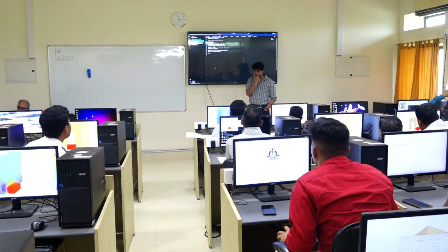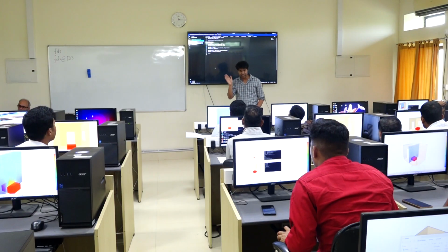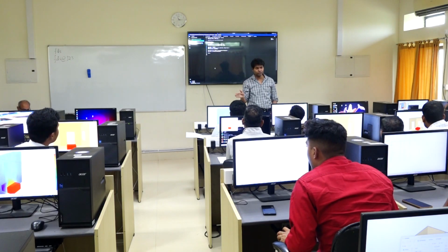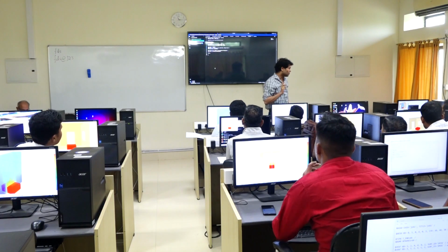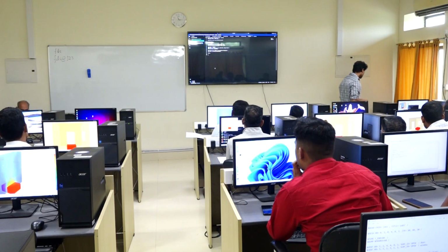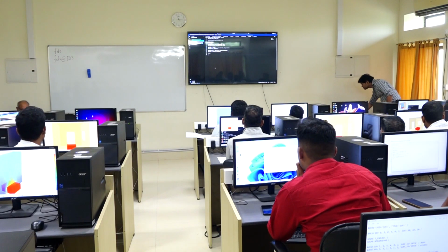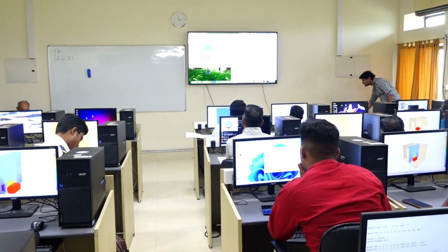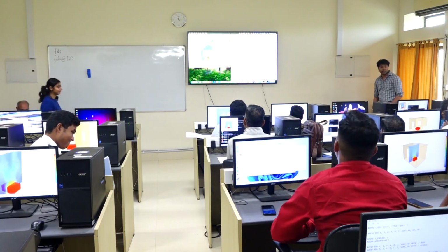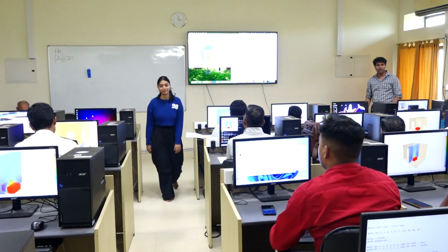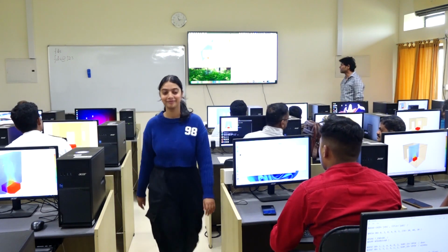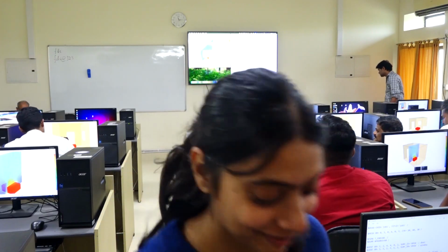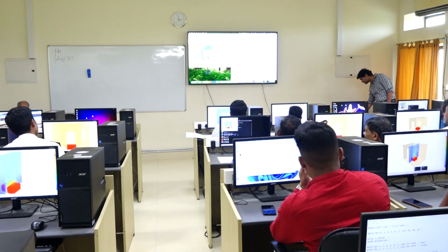So basically you told FDS to generate the temperature distribution at y is equal to 2. Okay? So when you go to Smokeview, in the temperature, it is giving you an option for y is equal to 2.